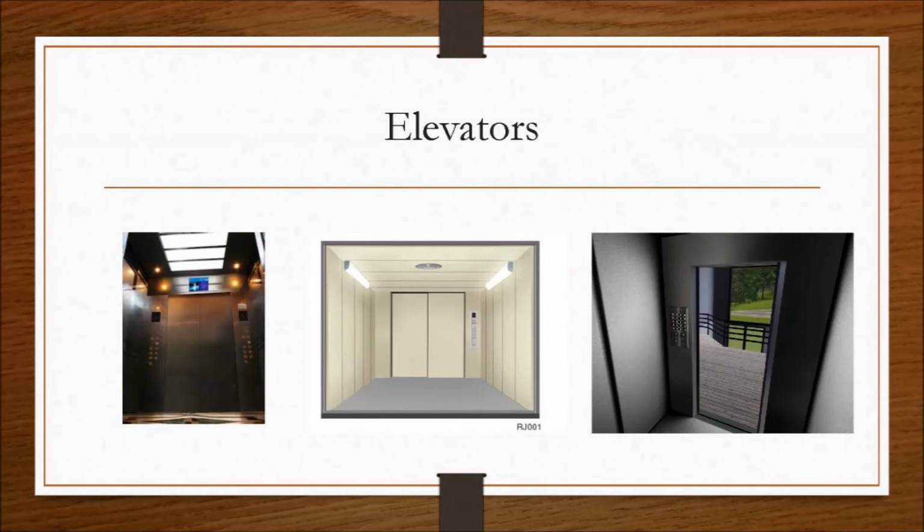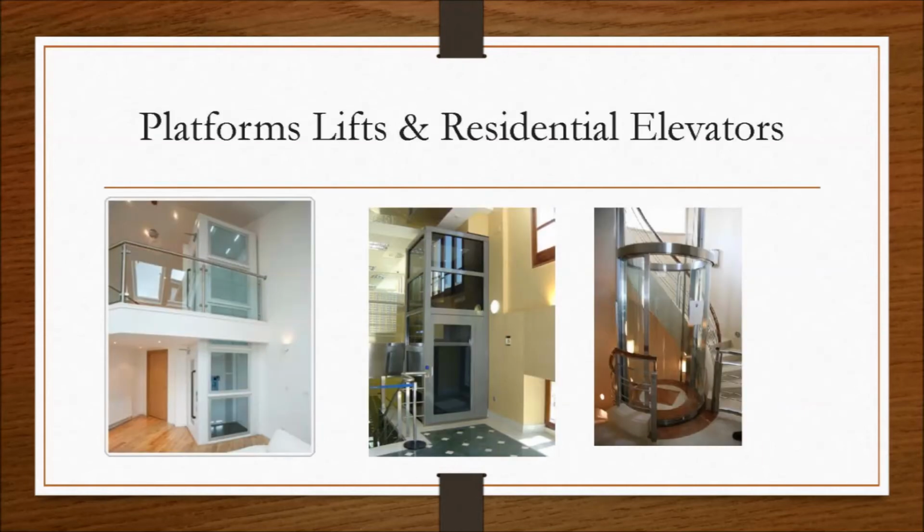Incline elevators are cars that ride up a diagonal path on incline rails, pulled up by a traction cable. Vertical platform lifts are safe, economical, and space-conserving ways to overcome architectural barriers up to 12 feet high. These lifts are an alternative to elevators for limited rises. Vertical platform lifts do not require a hoistway or runway. Enclosure may be made of steel panels or clear or tinted acrylic panels.